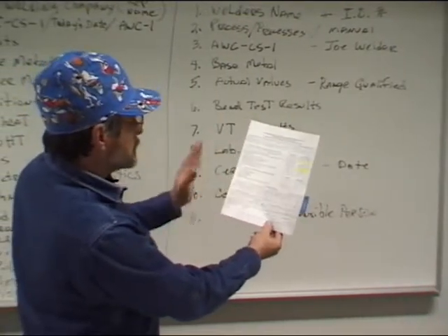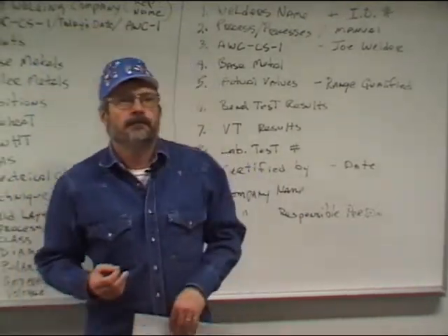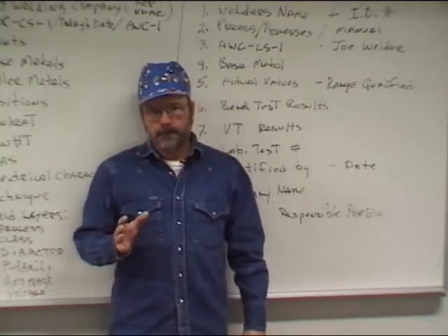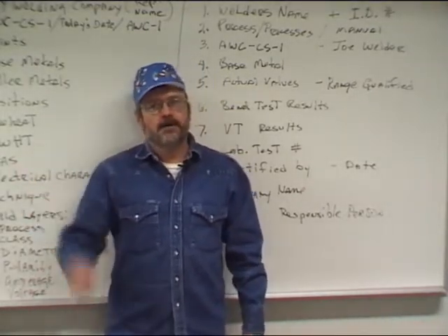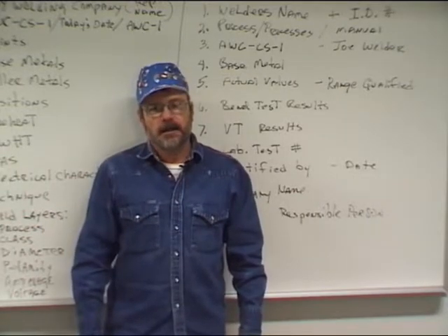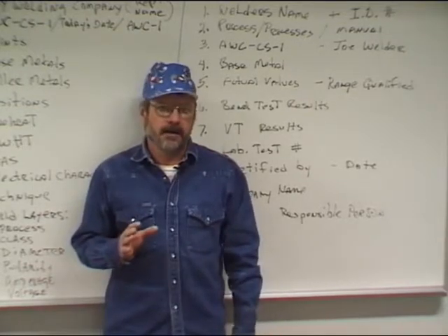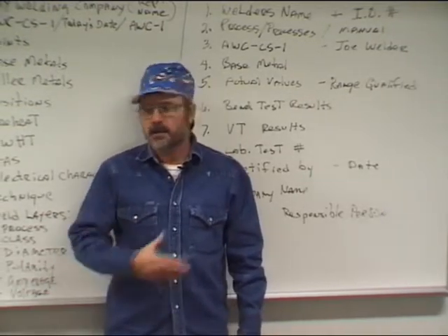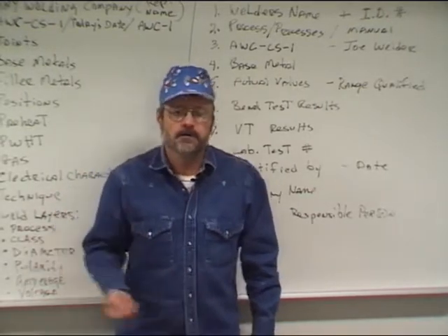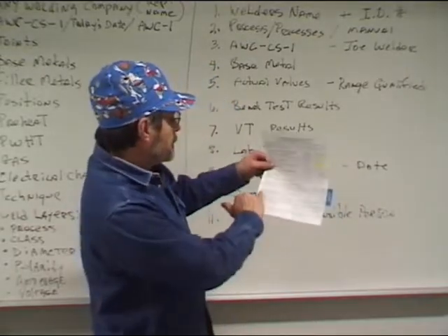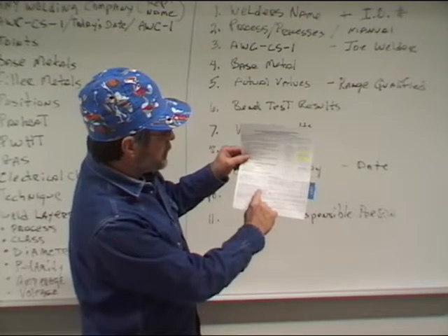Visual examination, acceptable. Radiographic test results. Well, ASME allows a welder to do a production weld. You can actually put a person out there and he's not tested. But you've got to x-ray the first production weld that he does. And if that passes, then they're acceptable, they're qualified by x-ray, because x-ray is considered to be a soundness test, the same as bend testing, because it's looking for any discontinuities or defects within the weldment. So you could do that, and if you want more information on that, look at QW 304 and QW 305.